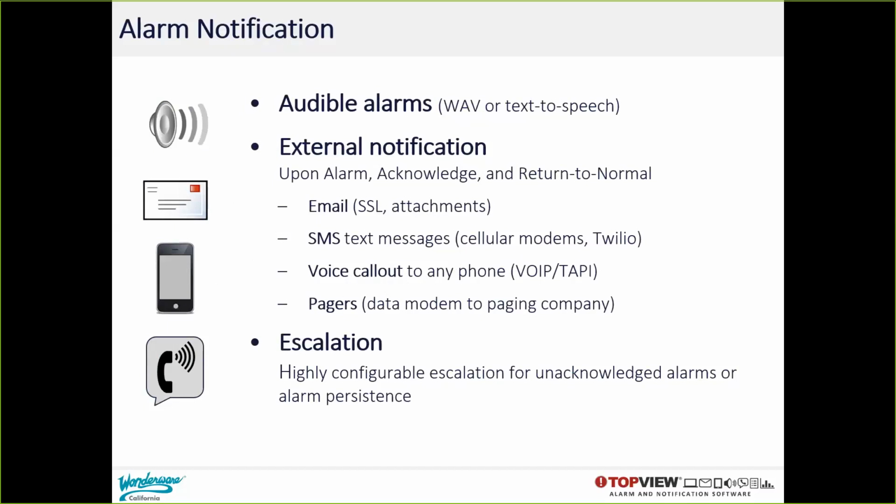With TopView, you're not limited to notification just at the time of alarm. We also support notification upon an alarm acknowledge and return to normal event, with the ability to customize the notification message and recipients for each of those events. And you can easily escalate your notifications for persistent or unacknowledged alarms.